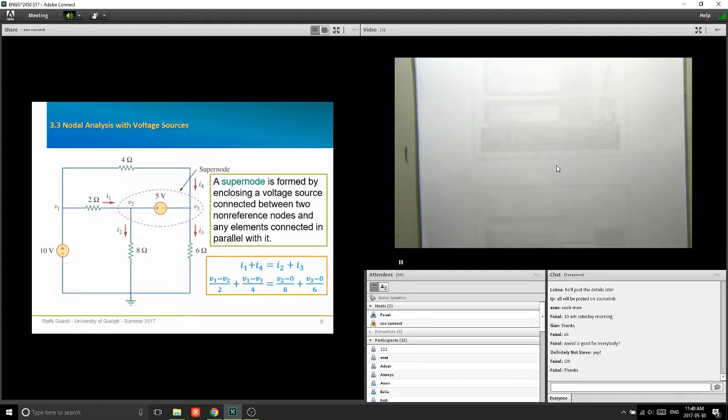I'll tell you what you can do. You see that voltage source that's there, that 10 volt source? By definition, we know that a 10 volt source maintains 10 volts across its terminals. So if the bottom terminal is connected to 0, then the top terminal has to be 10 volts higher than 0. That's why from this 10 volts, I already have the solution for V1.